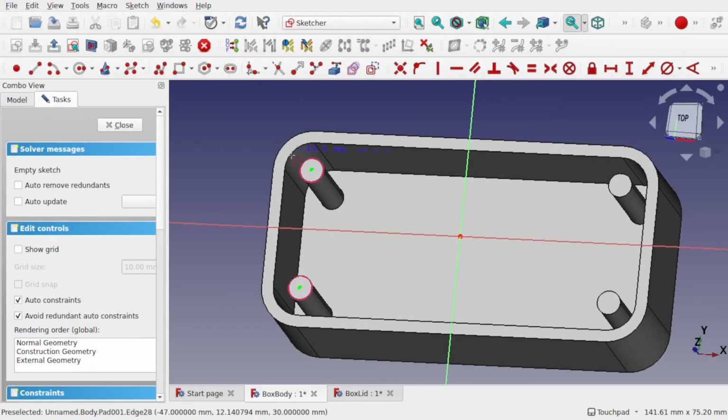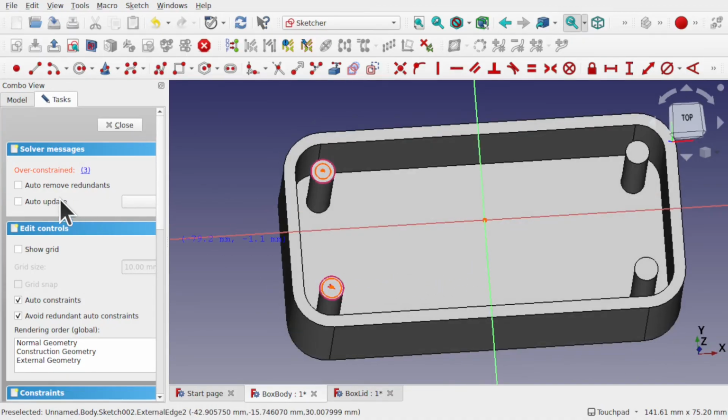And then I'm going to create two circles just inside. Make sure you don't touch anything, because otherwise you can end up placing those tangent to this circle. So if I try that, come into the center and I touch that circle there, you can see you've got tangency coming up and it'll come up as over constrained, and we don't want that. So I'm going to select that and hit delete, and we'll make sure that those circles are okay.